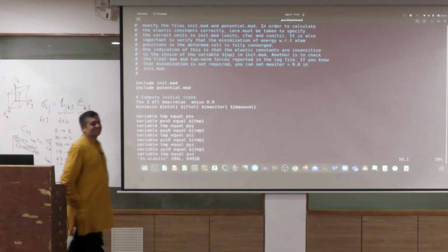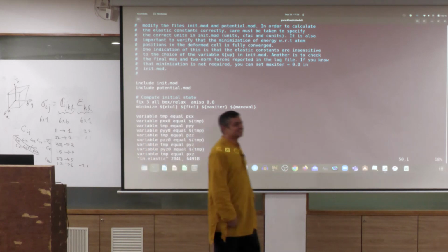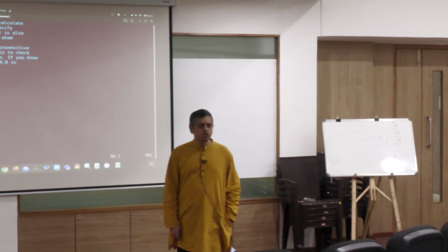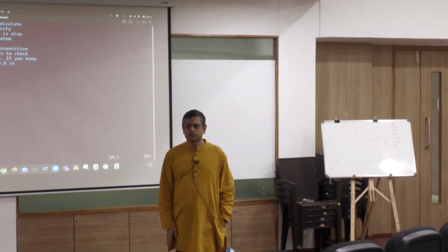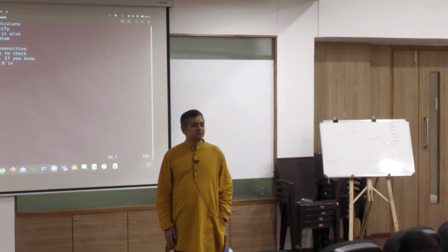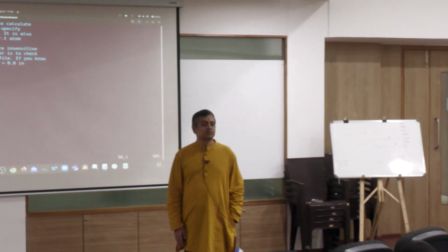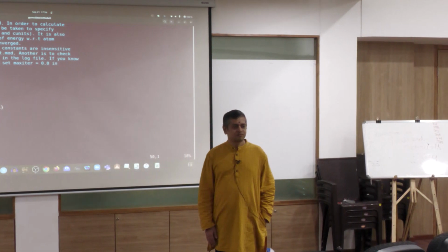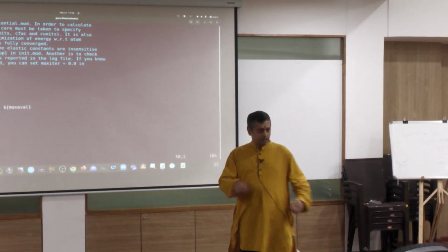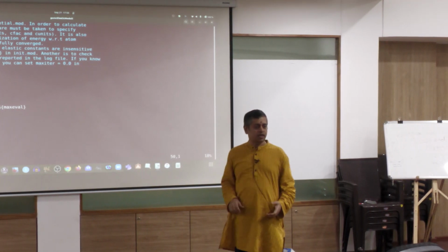Sir, my system is now the structure that I have defined, it is still cubic, it is diamond cubic. Okay, sir, because I am finding the elastic moduli now, in that case the deformation might not be similar in all directions. Yes. So, when I pull in one direction, it is going to break the symmetry.